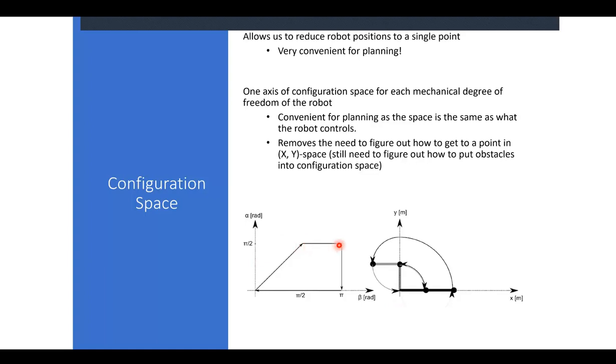And then you can see as we trace this out, I'll take my beta to pi, right? So it's going to go 180 degrees, and then I'm going to bring alpha back down to 0, and then bring everybody back to 0. And so the robot will do this kind of flailing motion that's traced out by these arrows over here before laying flat down at the bottom. So when we talk about configuration space, that is in terms of the robot's joint angles.